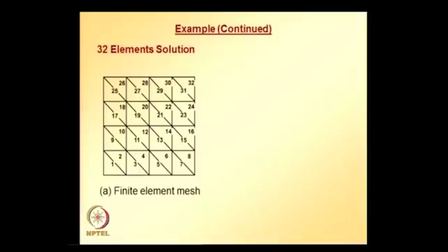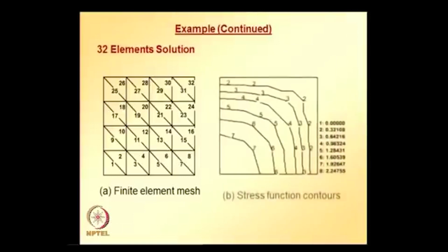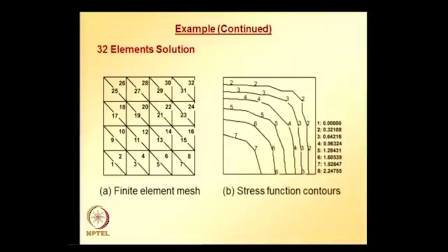Solving those equations, we get the stress potential at other nodes, and then we can do interpolation for calculations of stresses and torque, and the stress function contours are given here.